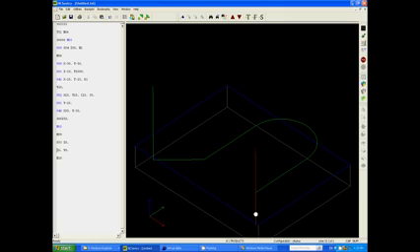We're using the machine's coordinate system, so we're going to send the table home in X and Y. Now the last line of code is an M30. And what an M30 does is it runs a program that's in the background, which is probably executing quite a lot of different little functions, like it will turn your spindle off, coolant off, all that kind of stuff. But it'll also reset the machine to default modal settings.